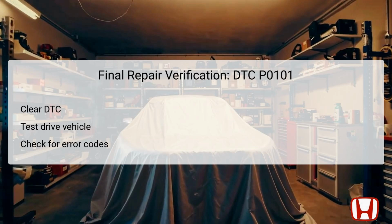On completion of repairs, it's crucial to verify that the issue has been resolved. Begin by clearing the stored DTC from the PCM memory. This step allows the system to reset and will enable you to monitor any new codes that may arise.